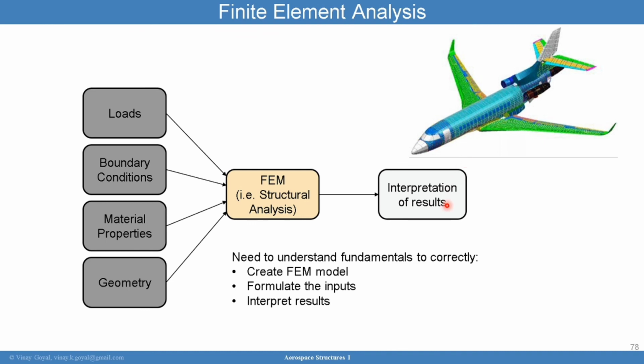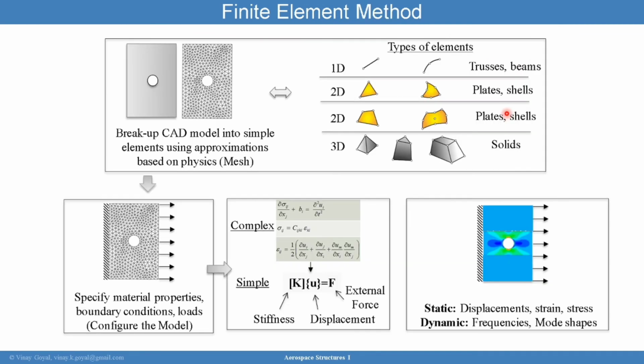And what is quite incredible, and I want to repeat it one more time, is that you could have millions of degrees of freedom. And these 15 equations and 15 unknowns in a partial differential equation would be highly complicated to solve over an aircraft, especially when you have a very complex shape like this one. Just imagine trying to solve it for even a simple cylinder. That would be very complicated. But we're able to perform a mathematical miracle and turn the problem into stiffness matrix times deflections equals force.